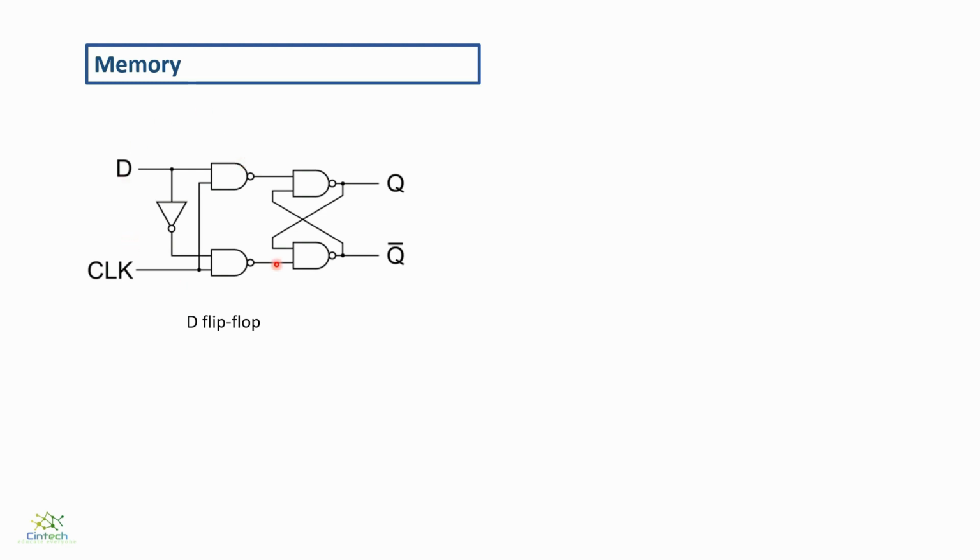Forget about memory. From basic electronics knowledge, try to answer this simple question. How do you store a bit? Right. It's a flip-flop. It's a simple D flip-flop. And it's very interesting. Say you have sent a clock pulse and have made the D bit high, that is 1. So Q becomes 1. Now make the clock low and make D 0, 1, whatever. It's not gonna change. It's latched. So you see, flip-flops are ideal memory elements.